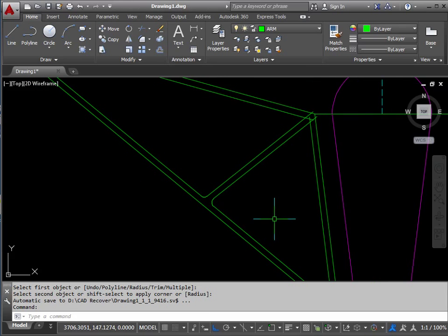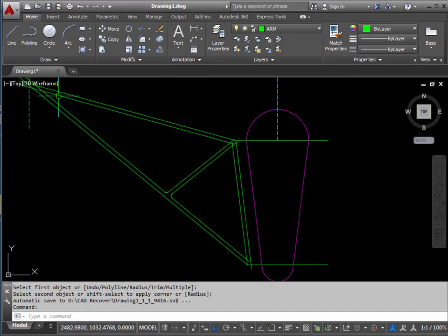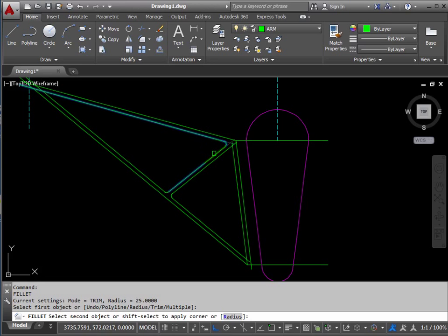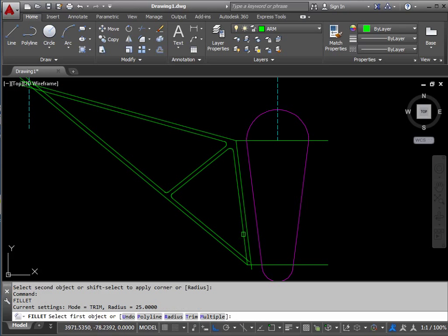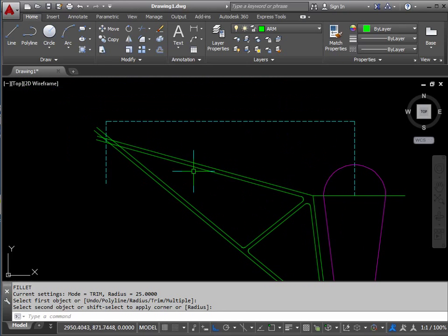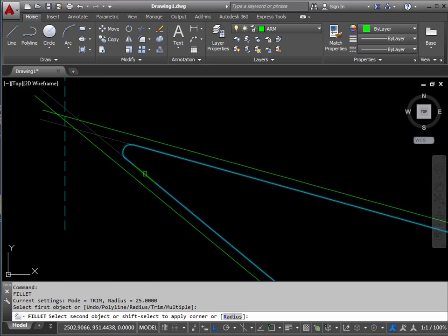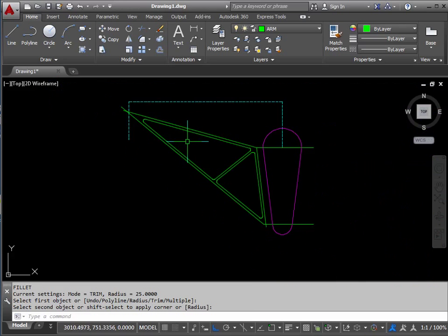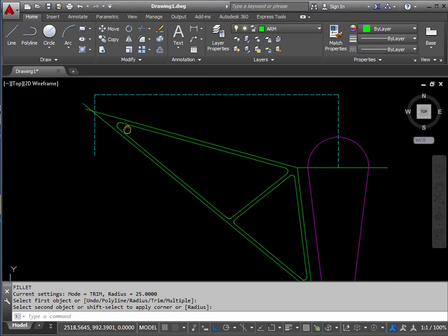It's starting to look much more interesting, like a bicycle frame. So all the interior connections are rounded, the exterior ones are angular. So press return and tidy up all your interior connections, returning in between to use the command again. It's nice and quick. Press return again, and the final one, return again, and this will shorten these quite a bit, but it definitely looks like a sporting bike frame or a motorcycle component, something like that.